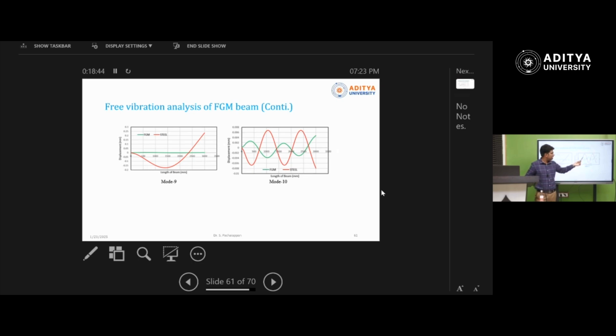So wherever we are getting the peak vibration in the beam, at that location we need to add more stiffeners to arrest that vibration. So we know which part has more displacement. In that part, we are going to increase the stiffness by attaching a steel plate on both sides of the beam, the soffit and top of the beam also, so that the stiffness will be increased in that particular place. We are going to avoid this red color peak.